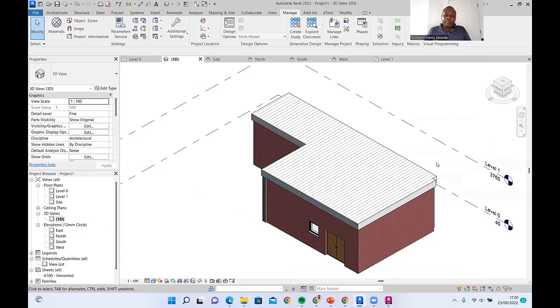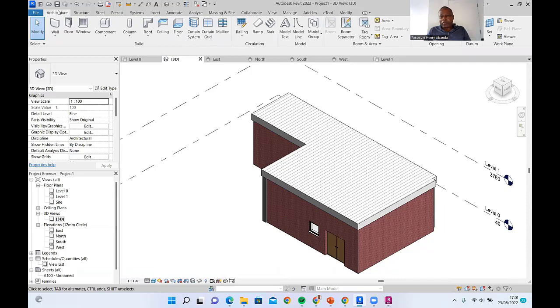So that is basically, so we could add other components just as we would have done in a typical Revit modeling. Okay. So that is how we bring our point cloud from Autodesk Recap into Revit, and then use a kind of tracing to be able to generate a model like this. And based on this, now we can do different things. We can do quantity takeoffs. We can export it. We can even evaluate the embodied energy of this model. We can take it to other software systems.